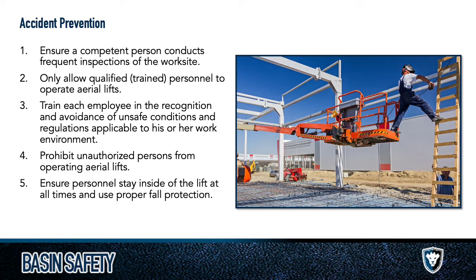So accident prevention is pretty much number one when it comes to operating an aerial lift. Unlike a forklift, unless you're operating a scissor lift, these typically have some form of articulation to them, which again, with your center of gravity, same thing, it's going to move with the weight on the equipment. So we want to make sure that a competent person is inspecting not just the equipment, but also the work site. These things are designed to be level and flat, and a lot of them are used in non-level areas, such as work sites and pads and locations, and even out in the back in the yard. And so we want to make sure that it's good conditions.